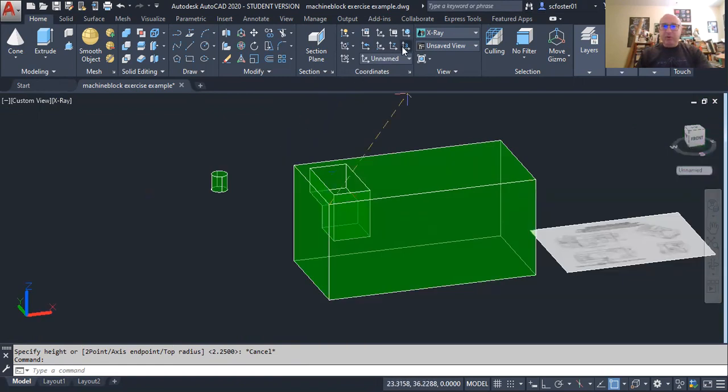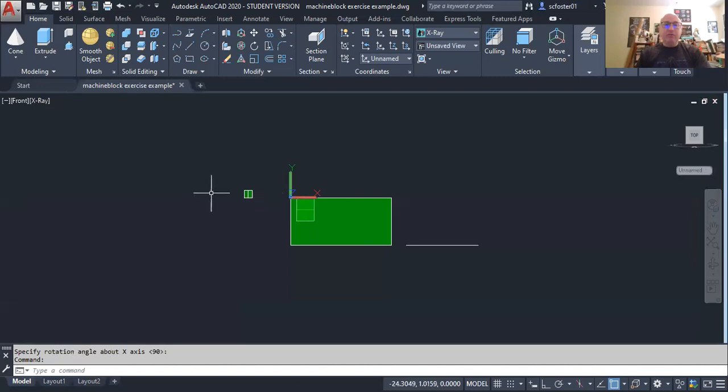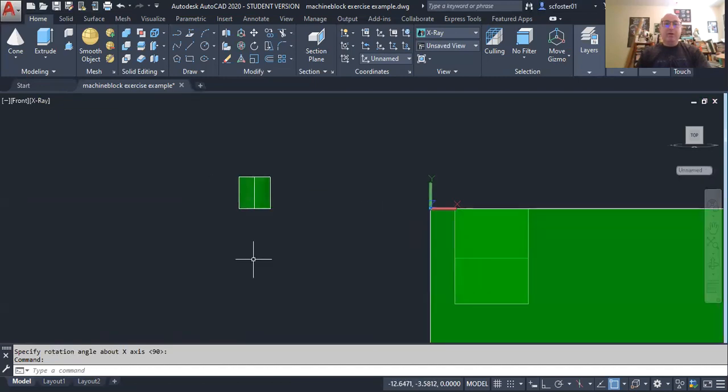You can use the 3-point, pick the bottom corner as your origin, something along X, something along Y. Really straightforward. It's the easiest way to do it. If you feel a little bit more confident, you can just pivot along the X 90 degrees and just hit enter. Okay, now I'm looking straight on. So I'm going to change my view cube so I'm looking straight on, and here's why. I want to create that angle, and I'm going to rotate it.